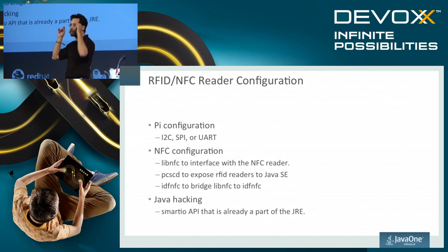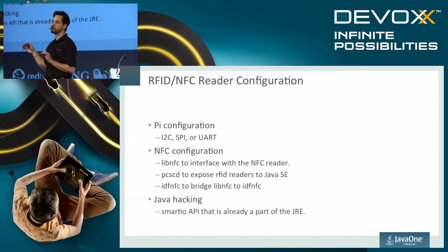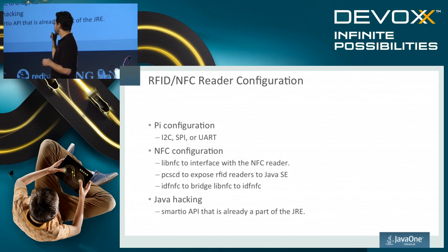And then you use libNFC to actually set up communication to the chip. You can use nfc-list to get the devices. But to expose it to Java, libNFC is not enough. You need to get a PCSC interface where Java can use the Smart Card IO library. If you're using a USB reader, PCSC automatically hooks up to USB card readers with proprietary drivers, but if you're doing a real embedded project, you'd probably rather not use a USB interface. So there's a nice bridge between libNFC and PCSC called IFD-NFC, which makes your libNFC device look like a PCSC device to the PCSC daemon.